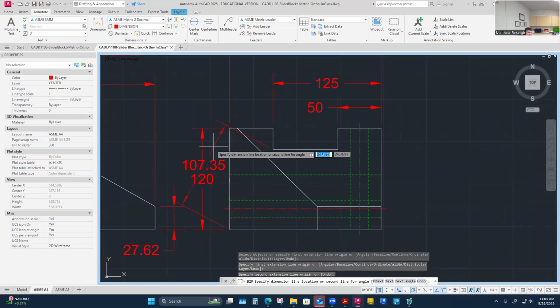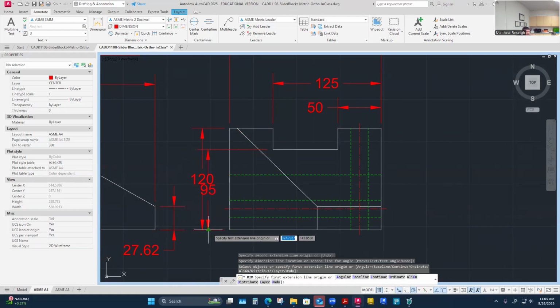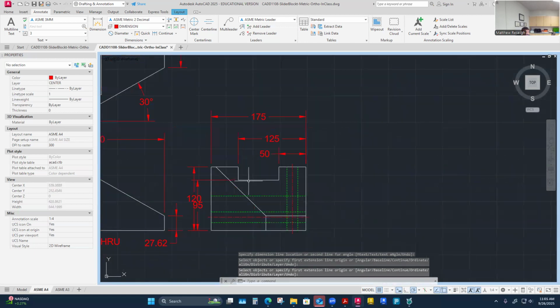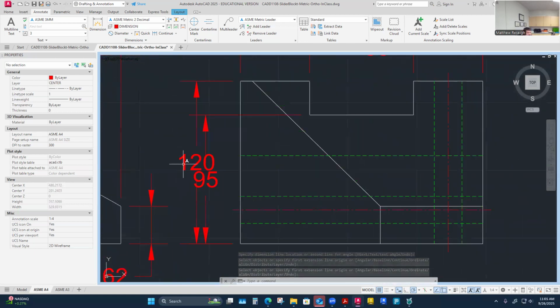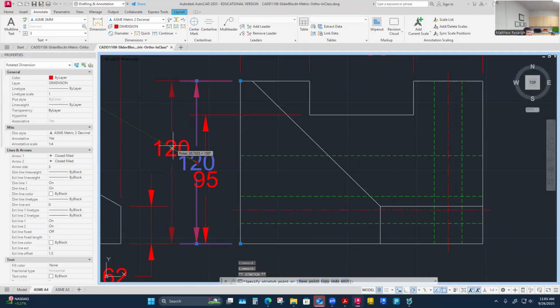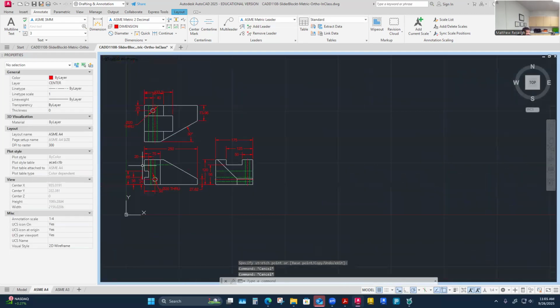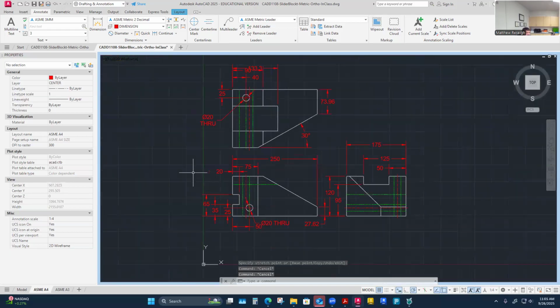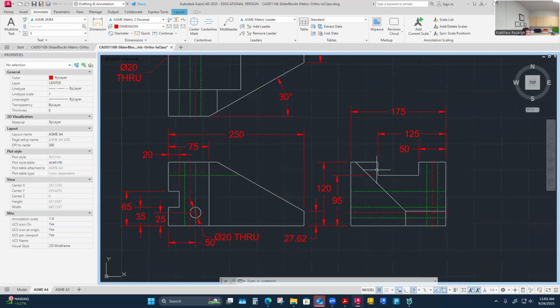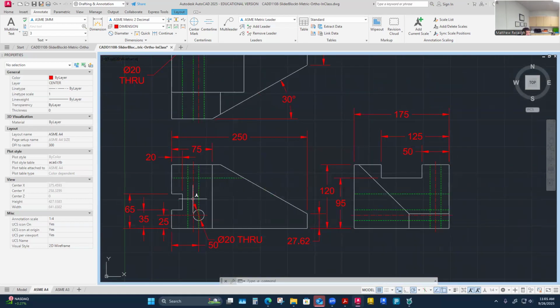I'd probably pull this right here to here, even though on your sheet it says 25, and that would be fine in week one of dimensioning, but I'm telling you that the bottom is definitely a good datum of most all parts. It's going to sit against a jig and fixture in any really critical environment. When this part got analyzed and inspected, it's probably going to sit flat on its bottom. It's going to be the first datum established. So this to me is a better dimension than top down. In fact, if you'll notice, I don't think I've done any other top-down dimensions here, right? I've done bottom up, bottom up, bottom up, bottom up, bottom up, bottom up.